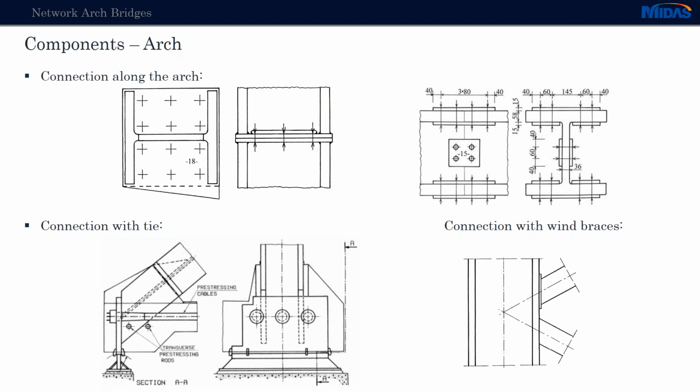The bolts in the flanges, for example, are structurally needed mostly just during the assembling, because there are no large bending moments in the arch, but these are usually kept in the completed structure as well.